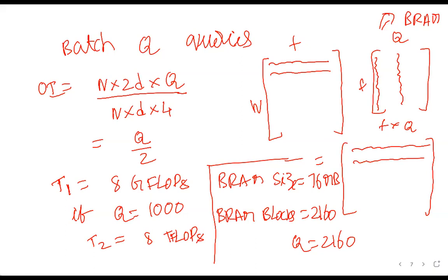It's actually a good question. Depending upon the application, sometimes this problem occurs, the question which Aditya posed. In many CNNs, in object recognition tasks, you have a feature vector followed by an FC layer, and the FC layer computations are very memory bound. If you have only one vector, then the FC layer on FPGA doesn't quite work.